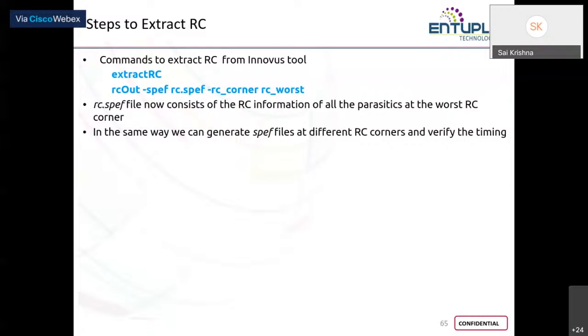So if you remember yesterday for timing analysis, especially the post layout timing analysis, to be precise, because our layout is ready. Once your PD is done, that is nothing but your layout. So for your post layout timing analysis, along with your design, your liberty file, your constraints, there is an additional set of inputs that you give for STA to happen, and that is your SPEF and SDF, right?